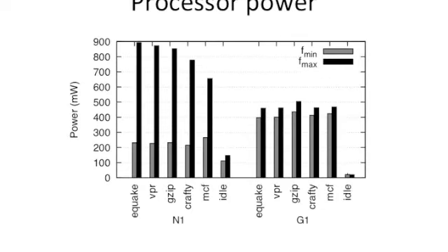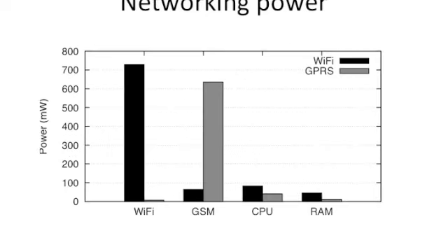I think it might vary. Pardon? If it is far away from the tower, it should transmit at higher power level. It should transmit, yes. The thing though is that the power consumption even for the GSM module has multiple components, right? And there is a power amplifier finally, of course, which is delivering the radiated power. And of course, if you increase the radiated power, the overall power consumption does go up. But how much of that is a fraction of the overall power? It will be a large fraction, but is it completely dominated by that? No.